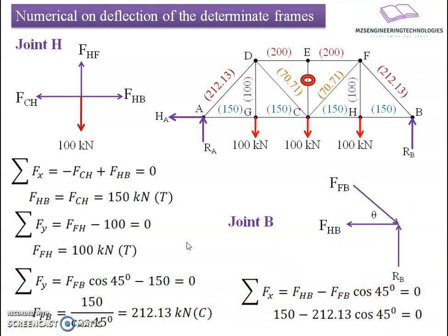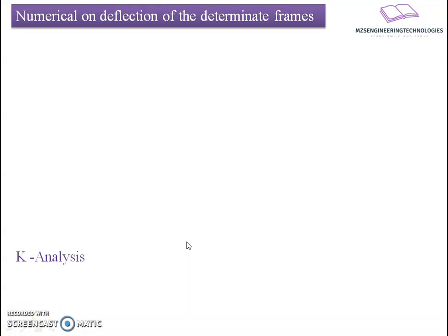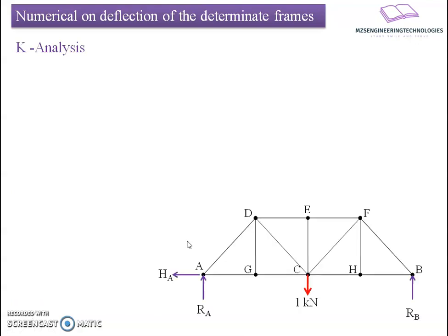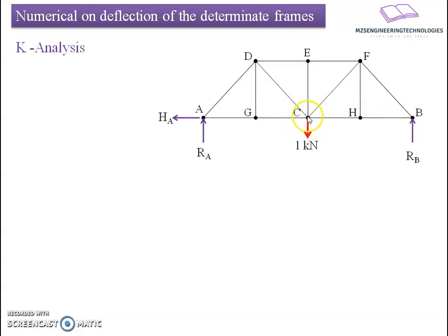Now I'm interested to know about the unit load contribution, because for analysis of finding out the displacement at a particular joint, we are going to apply a unit load at that particular joint, and we'll see the distribution of that unit load force among the members. For that we'll do the analysis here.